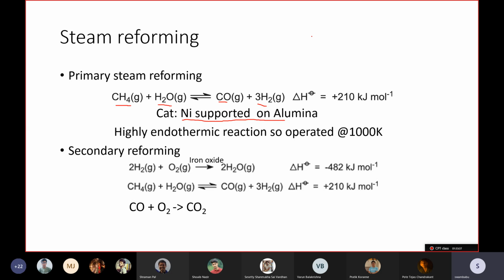So for any catalytic reaction, we always get a peak curve. It will go up. As temperature increases, activity goes high, and the favorability of the backward reaction also increases. So both go up: activity and backward reaction. The balance reaches a peak at some point, then the other one dominates. So we should always take the peak conditions.